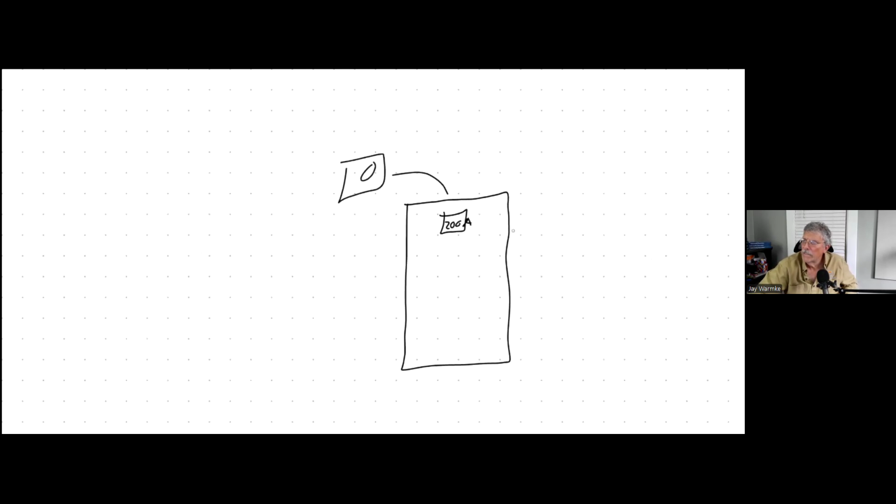What do we mean by the 120% rule within a load side connection? Well, let's say this is your circuit breaker panel box, and this is your main breaker, and you're getting 200 amp service coming in from the utility. And the box itself is rated for 200 amps. This just means that the bus bar that goes down the middle, where all the breakers are connected, if it exceeds 200 amps, it might melt just like wire. That's all the current it can handle.